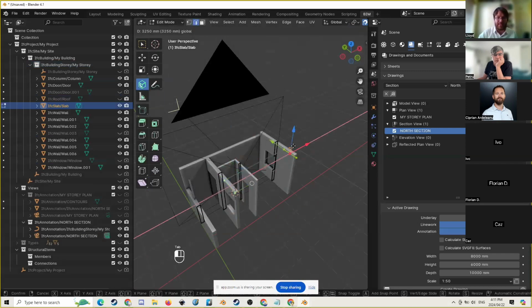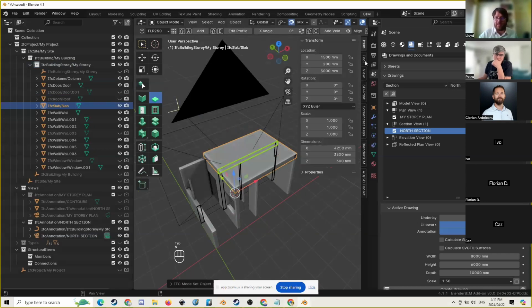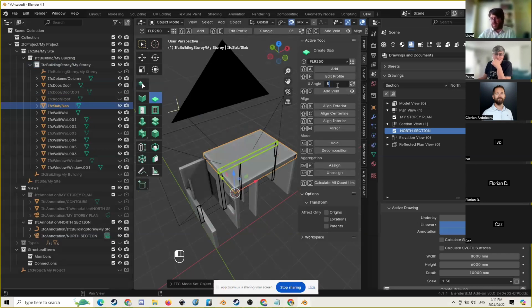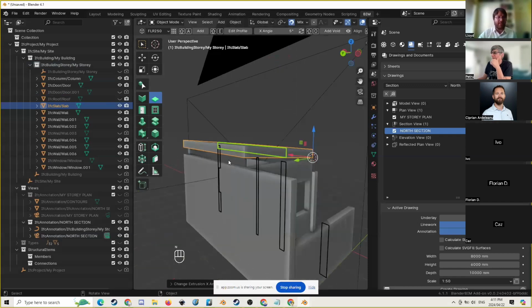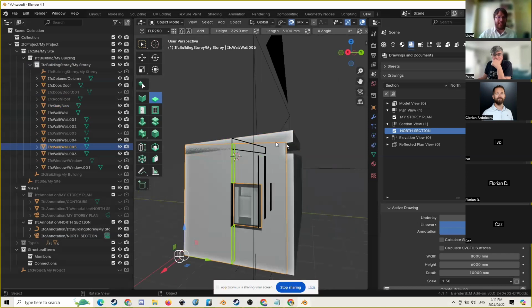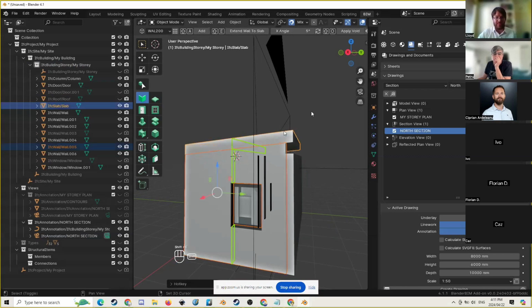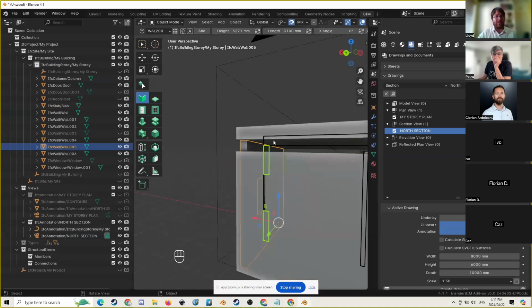And we edited the slab to be the right size and gave it a little bit of an angle, 5 degrees. Okay, so we've got a slab here, and it's also got a bit of an angle. So we want this roof to align with that. So this is the process. This is how it's supposed to work. It just doesn't currently work with roofs. So select the wall, you select the slab, and you press Shift E, and the wall aligns to the slab.